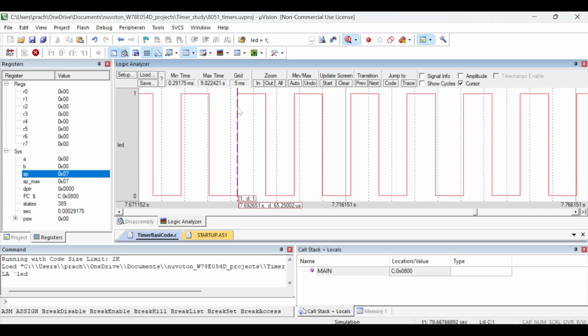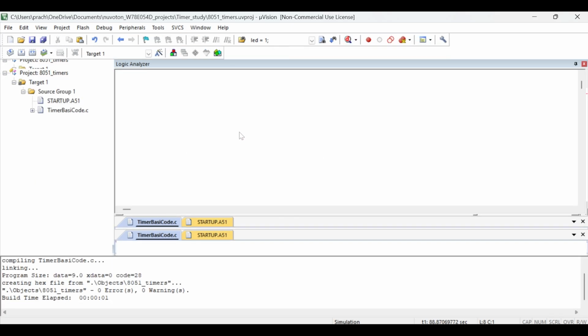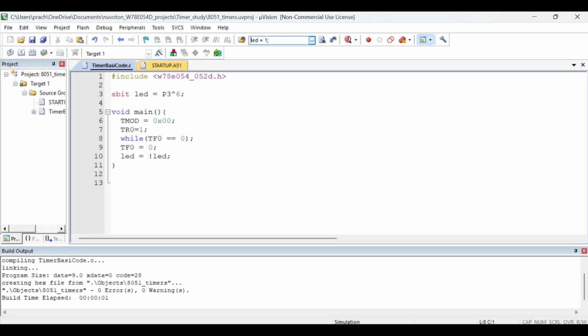So if you want to generate a square wave with T on and T off greater than 6.11 milliseconds, what to do? Yes, the answer is that we need to generate a delay like Arduino. So let's do that. We can generate a base delay of 1 millisecond and then run a for loop depending on the variable passed. Just like Arduino, we will make a delay function. Okay, so we will cut this and write here void delay.